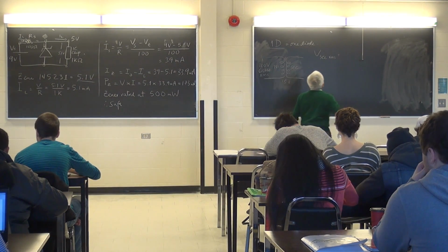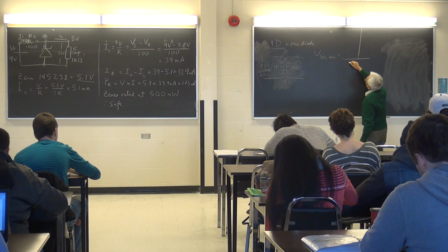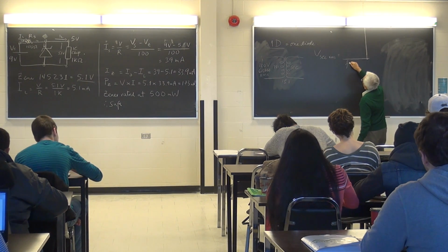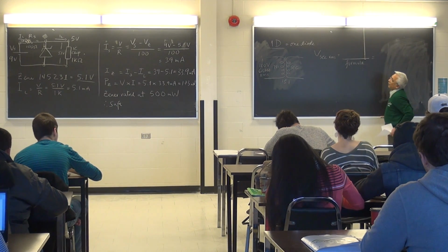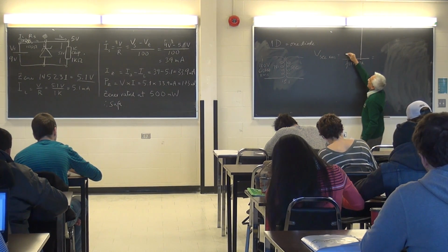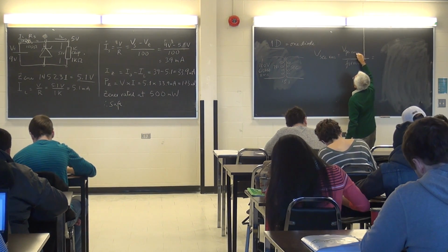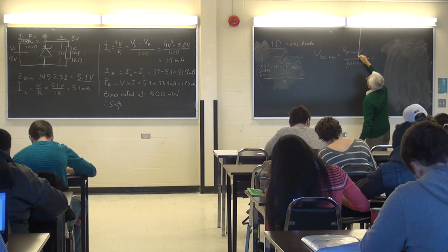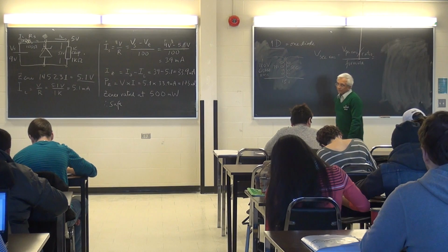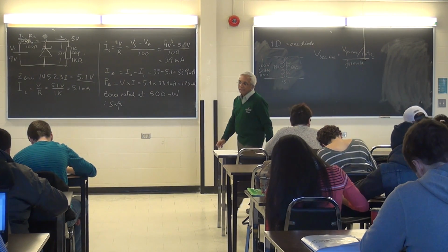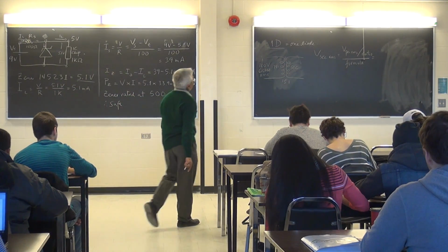When you are looking for a calculation, the first thing you're going to specify is the formula. So the formula for solving V secondary RMS is V primary RMS divided by the ratio. So we're stepping the voltage down by 15. So that's what the formula is.